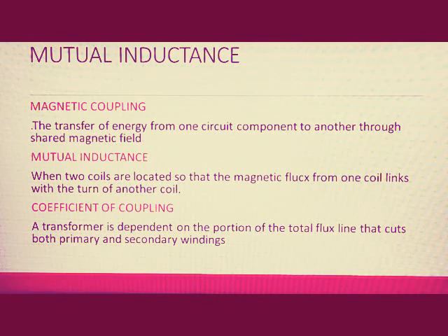Practical power transformers use a high permeability silicon steel core and close spacing between the windings to provide a high coefficient of coupling. Lines of flux generated by one winding which do not link with the other winding are called leakage flux. Since leakage flux generated by the primary does not cut the secondary, it cannot induce a voltage into the secondary.